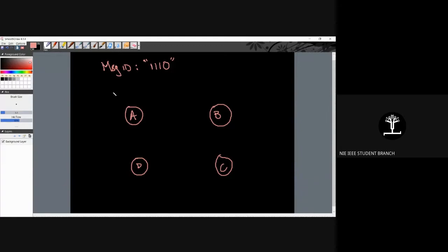Now let's say I'm in state A, and it's controlled by, let's say, a clear bit. Whenever I clear it, whatever is the state of the machine, it will come back to the initial state, that is A. So what happens when I get a 1? If my input is 1, I'll obviously go to the next state, that is B. My input is 1, but I haven't yet received the whole sequence, so my output is still 0. So that's how this works.